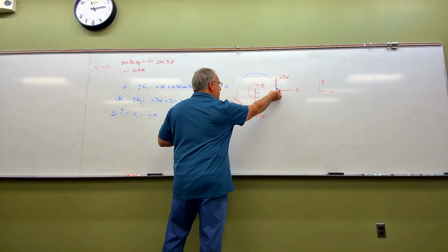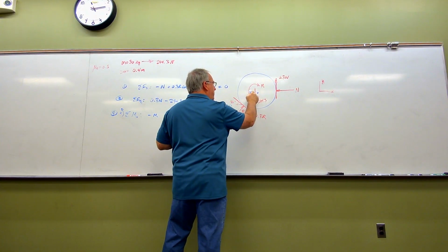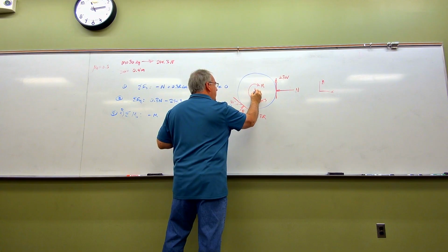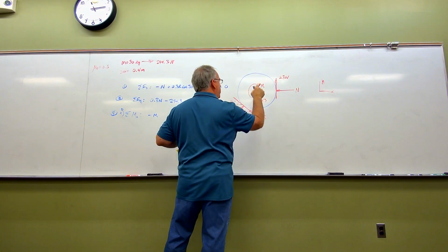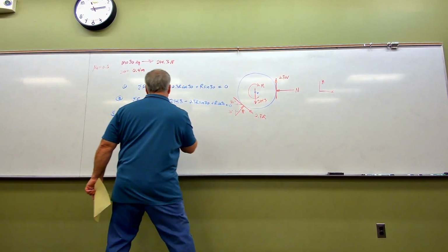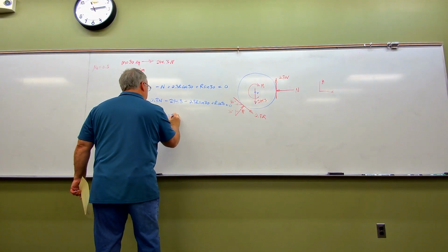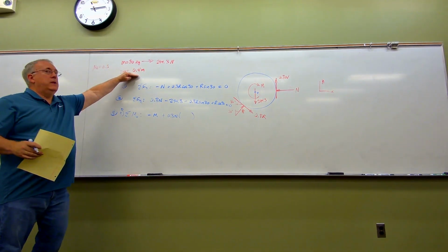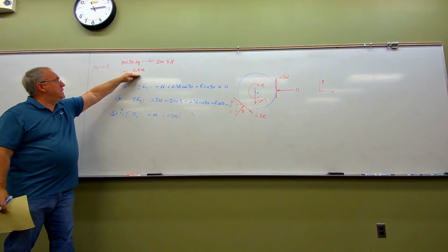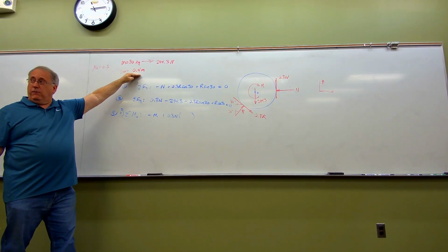And we see the way that that's drawn, with the moment center over here at point O, that would cause a counterclockwise moment about point O, so it's going to be positive, so plus 0.3N times the moment arm. Now folks will recall that we were told from the narrative of the problem that the diameter here was 0.4, right?